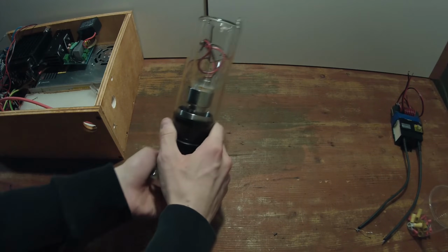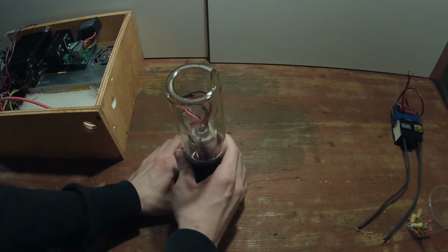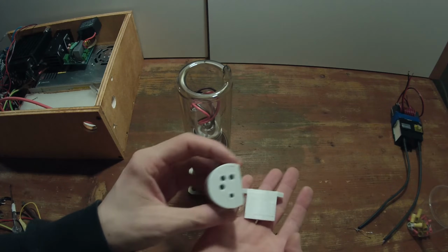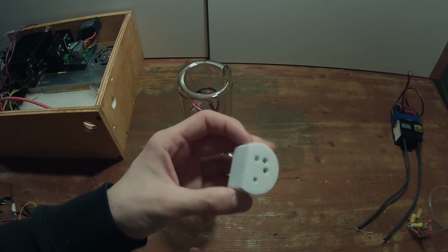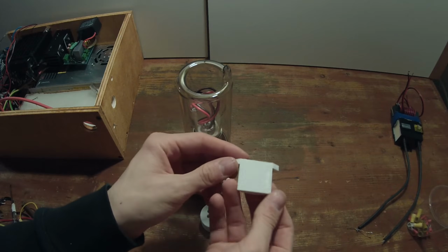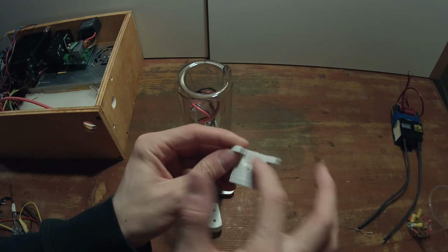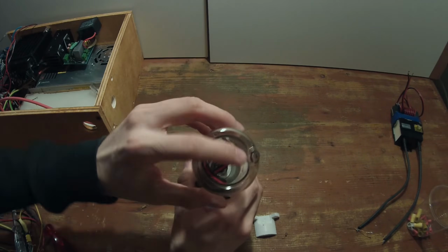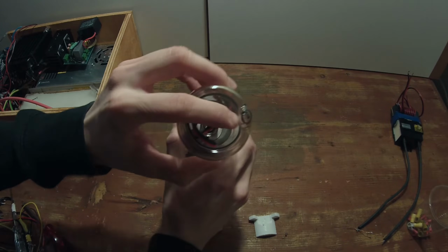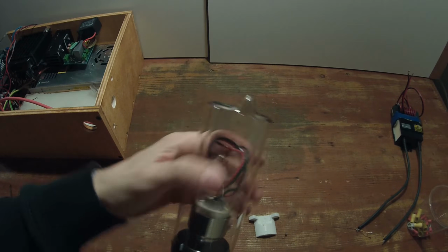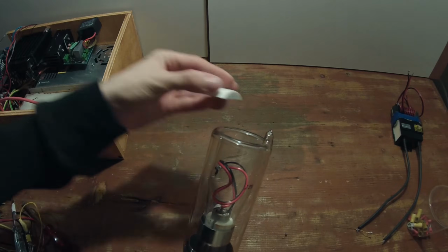This last clip shows you the high voltage feed through that I told you about earlier. It's made of two parts. That is due to the fact that the geometry of the tube is not perfectly circular, so the little thing you see me pointing at in the video needs to accommodate the glass of the tube envelope that is sticking a bit inside of the circumference of the tube.